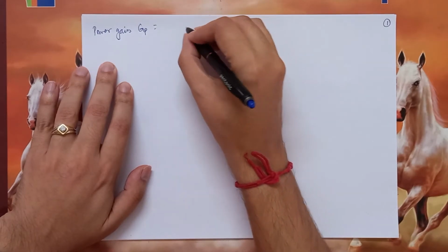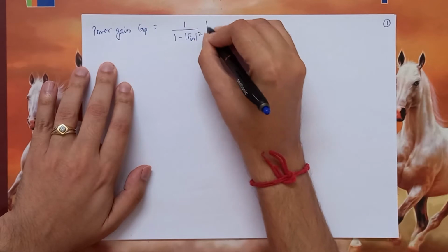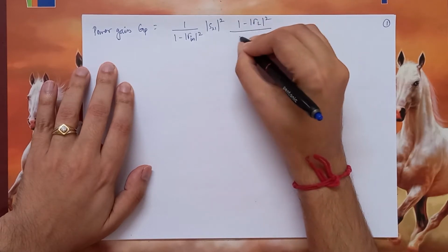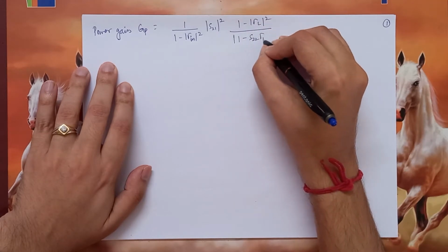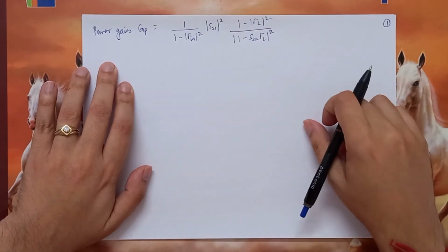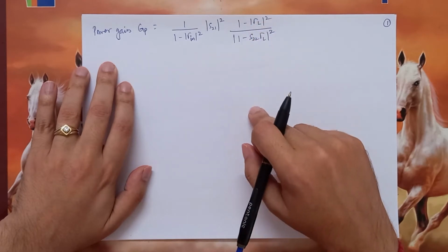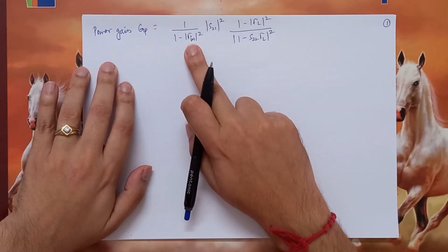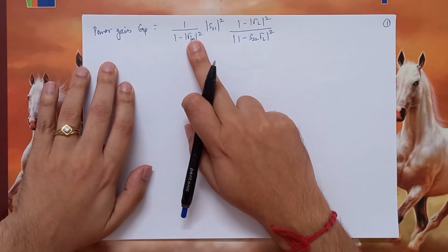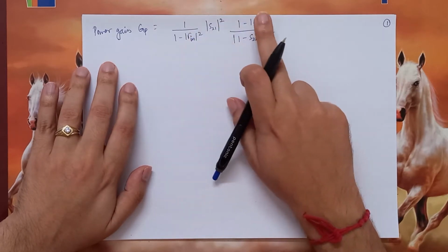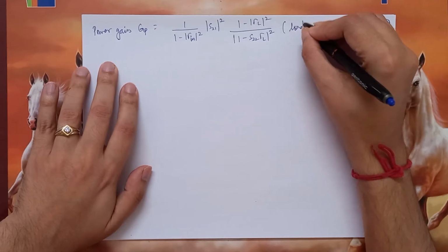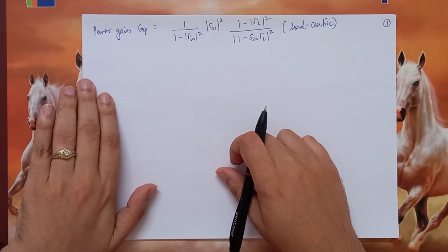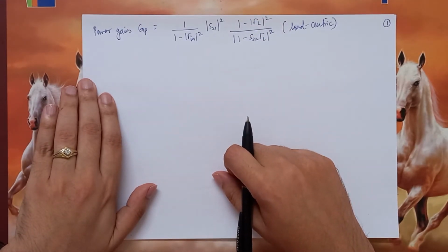The power gain GP looks like this. This is the power gain which we discussed was more load centric, because the load impedance plays a very important role. Therefore, you have the gamma L terms and gamma in, which is the reflection coefficient that you see when you are looking into the input port of the amplifier, which is also a function of gamma L. So therefore, it is load centric. And as we said, this expression is often used for power amplifiers, where we need to feed a certain power to the load. So the choice of load impedance is quite important over there.